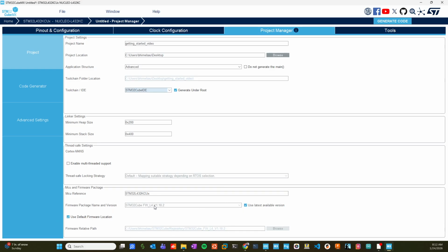Again, if this is the first time you're doing this, it's going to download some firmware, the firmware that you need for this particular processor, right? If it were to bring in all the firmware for every project, your disk footprint would be enormous. So it doesn't do that. It just brings in the processors that you use, and you can tell it which one. There are ways to configure CubeMX to bring in the processor libraries that you care about. Over time, as you load things up, it'll check to make sure they're current and go out and grab the latest one.